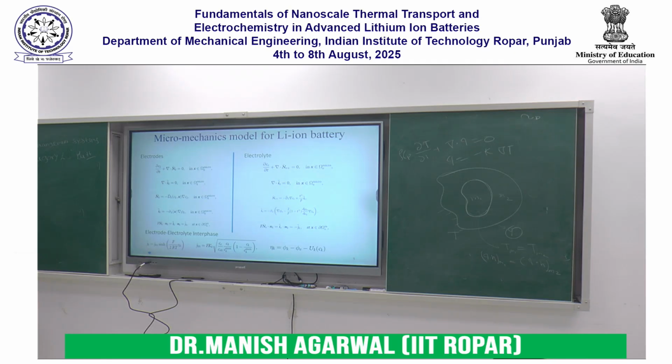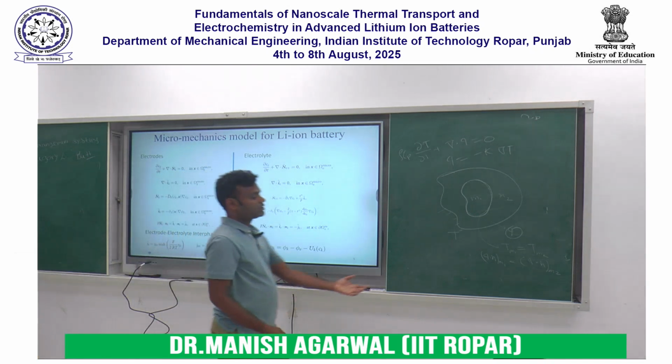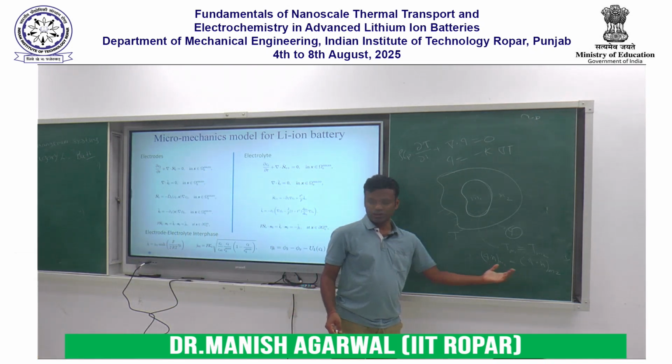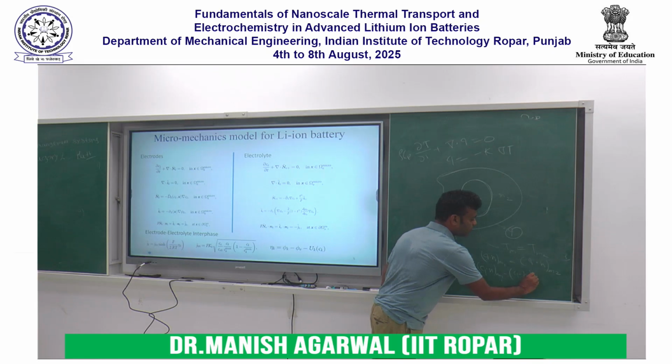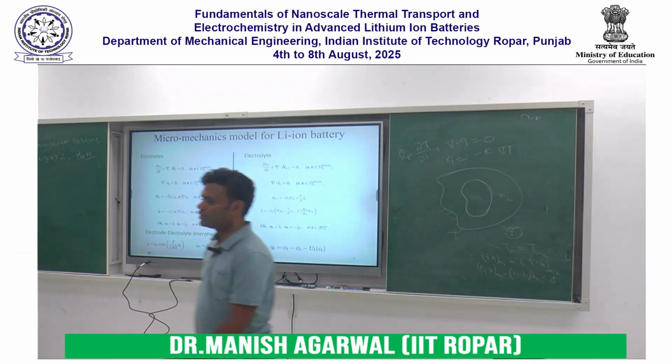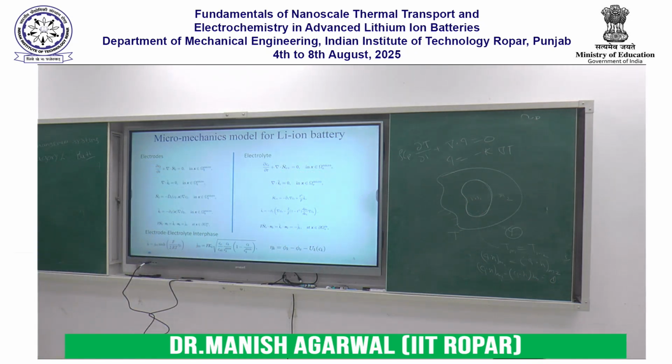Ultimately, there is some kind of heat source, right? Then this continuity of the heat flux will no longer be there, okay? Then it will be like q dot n in M1 minus q dot n in M2 will be equal to some kind of heat source that you have generated per unit area, okay?